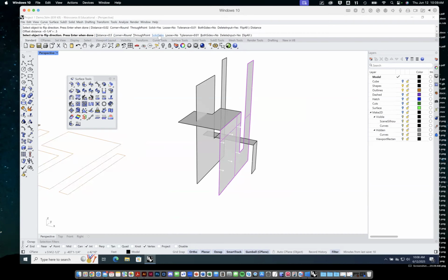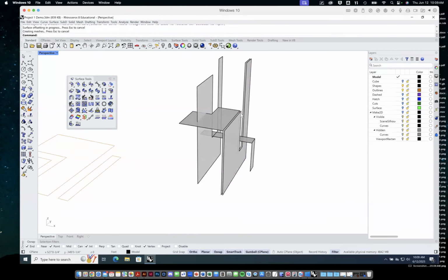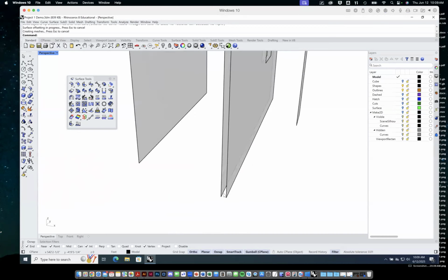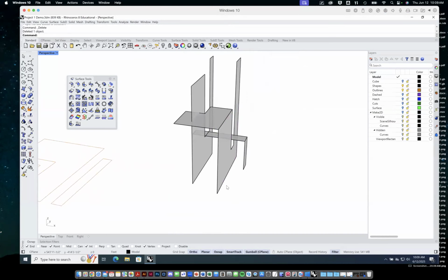By default, yours might say no. So if I say no and I offset this, you can see that I've just offset that surface perfectly perpendicular. But I can see in between these things, right? I didn't actually create any sides to this and create an actual volume or solid. Okay, so let me try that again. I'll toggle solid on. Distance still uses the last distance I typed in, so 0.5. That's good. I'm going to say solid, yes.